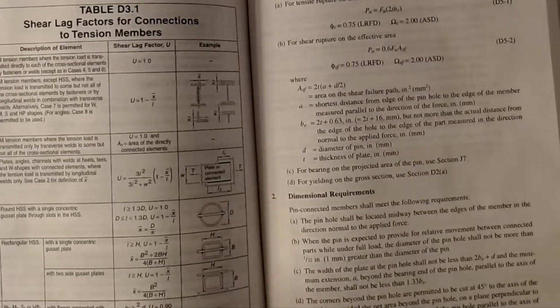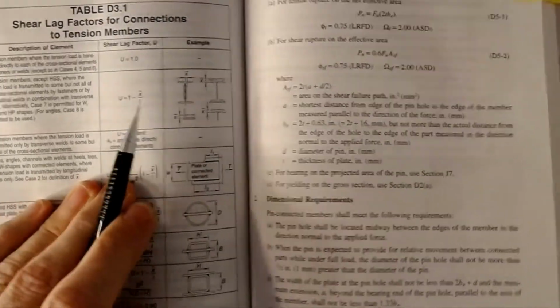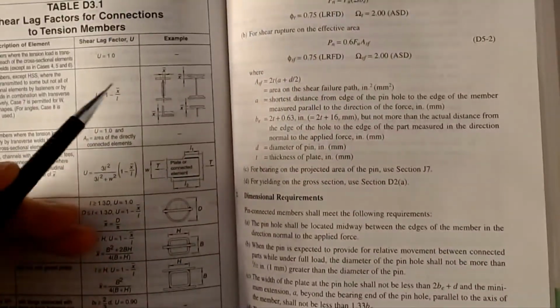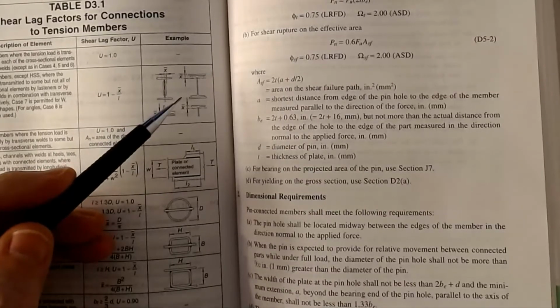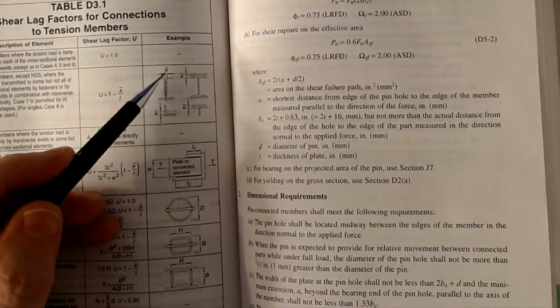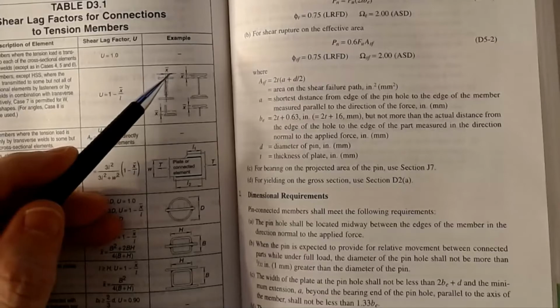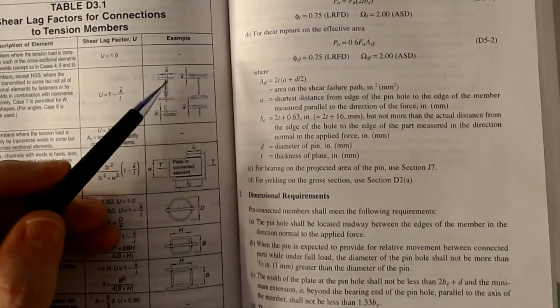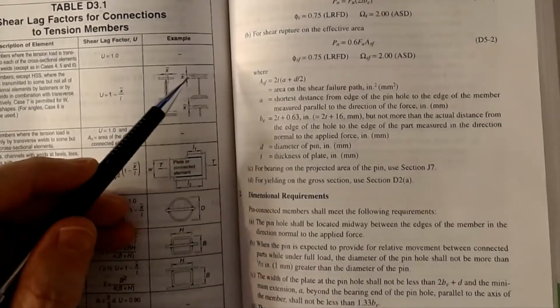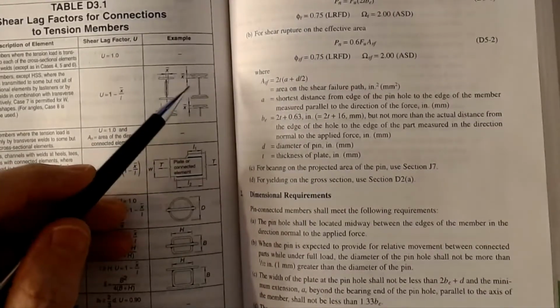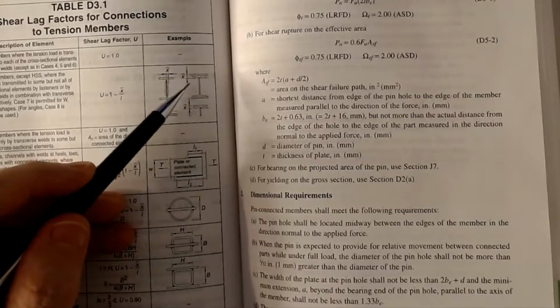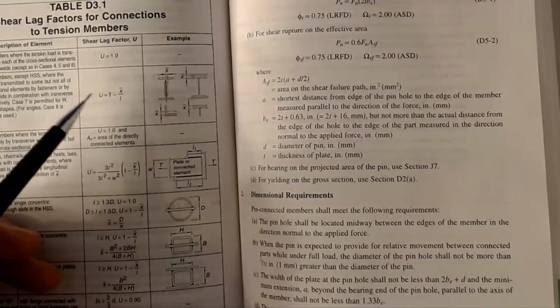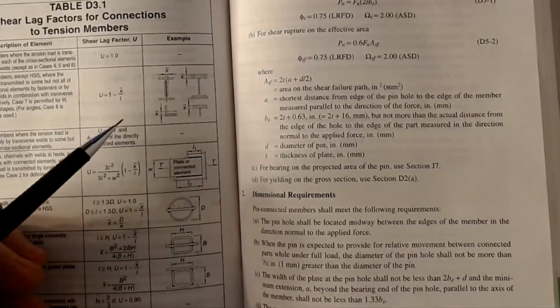Okay, and so they've got these little diagrams over here, and they're not real clear in here, but you can see that, for an I-beam in the Y direction, if they're welding to the plate, the X bar is taken from the center of the member out to the extreme edge of the plate. That's the X bar. If you're putting a plate on top or bottom flange, now it goes from the top of the plate down some amount X bar. Okay, well, the question is, well, what is X bar?